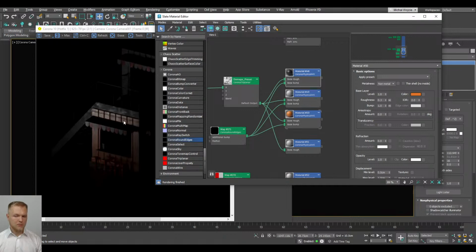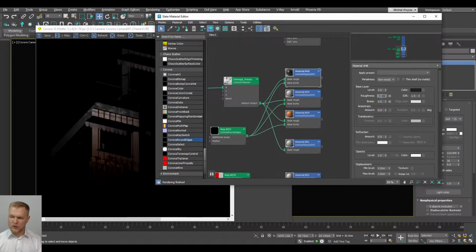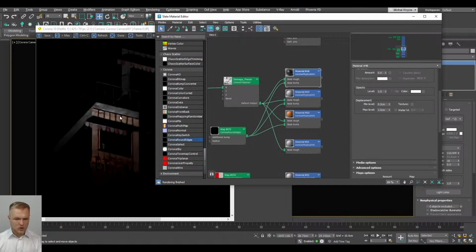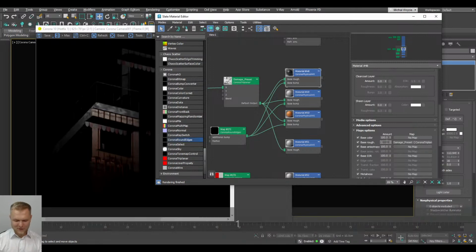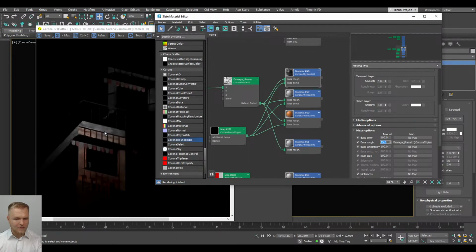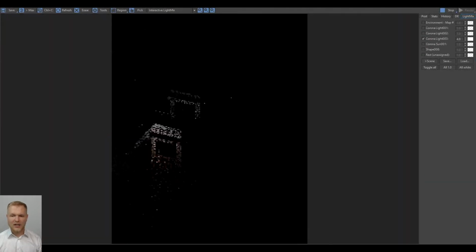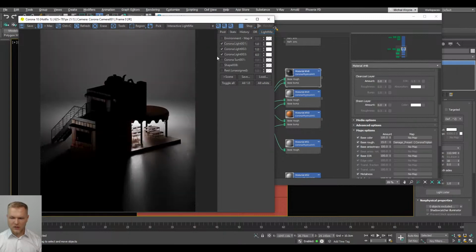I'm going to do the same for the metal, the black part, because I think it's going to need it. So let's go ahead and change the roughness to 2 actually for this one. And since we're on the topic, look how much more interesting it looks now in this reflection. And we're going to go for 15 for that part, because we want this to have subtle results. And now with all of the lights together, let's turn them on.